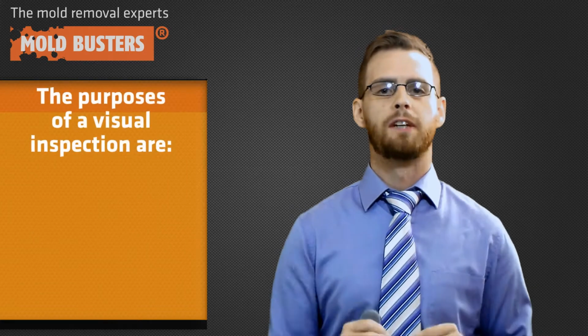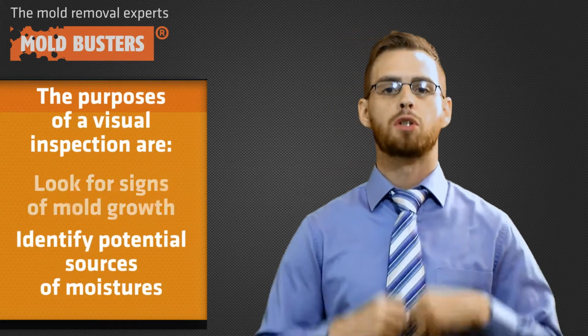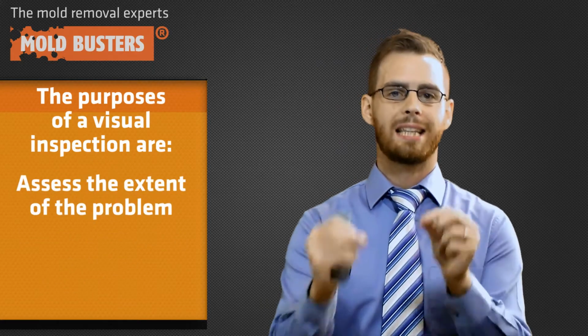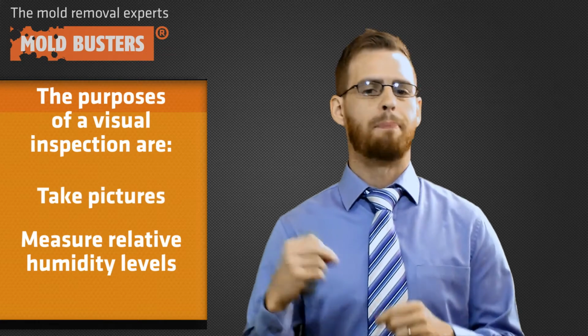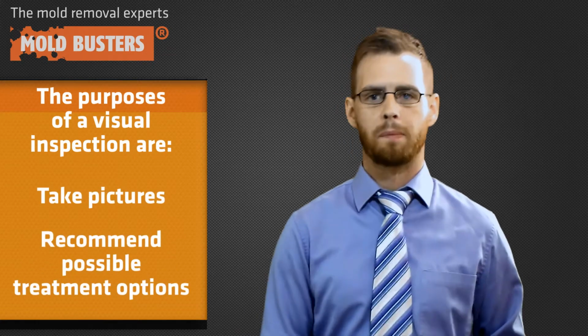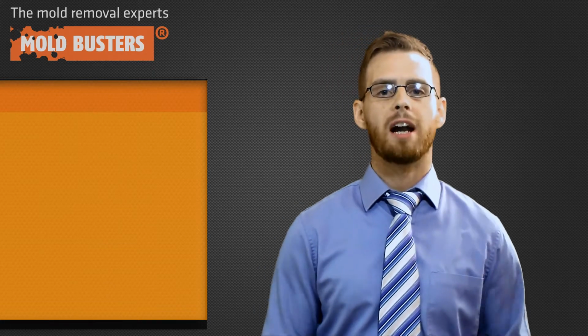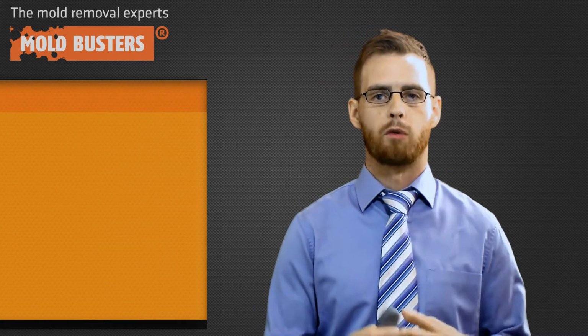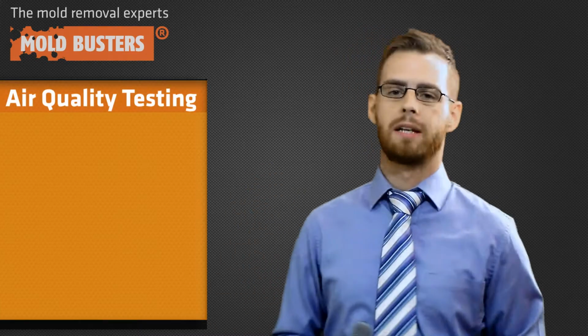The purposes for visual inspection are to look for signs of mold growth, identify potential sources of moisture, assess the extent of the problem, measure relative humidity levels, take pictures, and recommend possible treatment options. Although visual inspections are great, they don't provide essential data that's required for remediation. So that's why we should look at air quality testing.